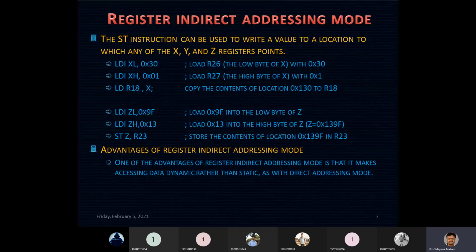In the same way you can have the ST instruction. The same is done with the Z register: LDI ZL, 0x9F, LDI ZH, 0x13.